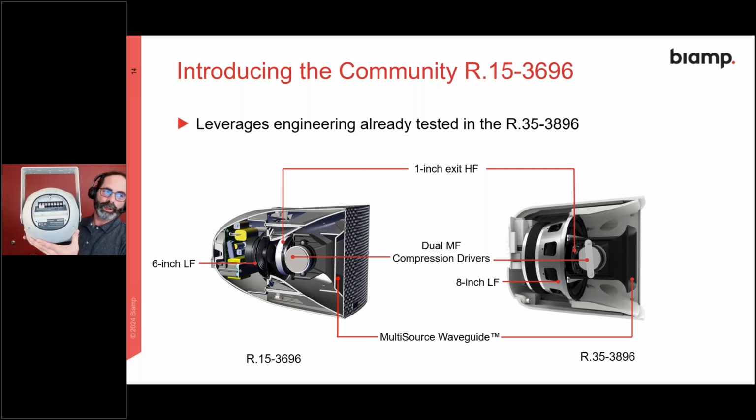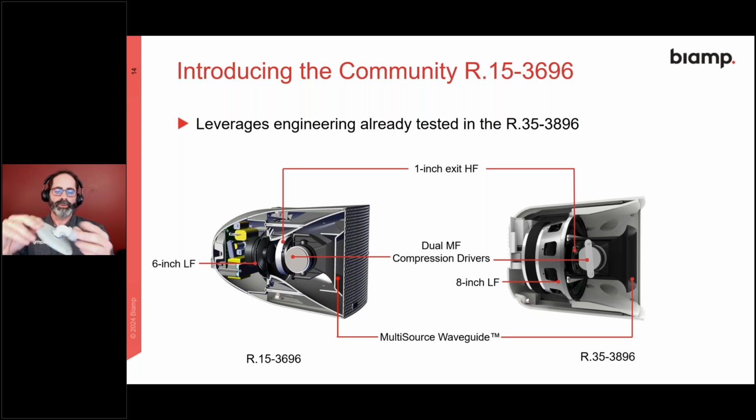The back's a conventional terminal block type termination. Another little change for those of you who already know R series really well. On the smaller models, we've been using an input cover that acts like a junction box cover. There's a gasket on the cabinet side. And we've added a turn to the gland nut. A lot of times folks are taking the wire directly straight in. It's a good way to get water into the cabinet over the long haul. This forces the installer to put it in with a proper drip loop. So a couple neat features there.